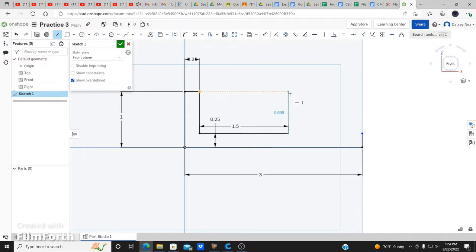You've got to see the indication, those letterings right here, the one that disappeared. It gives you the indication that it's already parallel, already horizontal and vertical. So I'm going to click it right here, and that'll activate it. I'm going to bring this over here on the outside, which I'll dimension later on. Bring it down here, that'll give me the exact height. And now what we would do is finish the last one. There we go. So I'm going to cancel my command with escape.